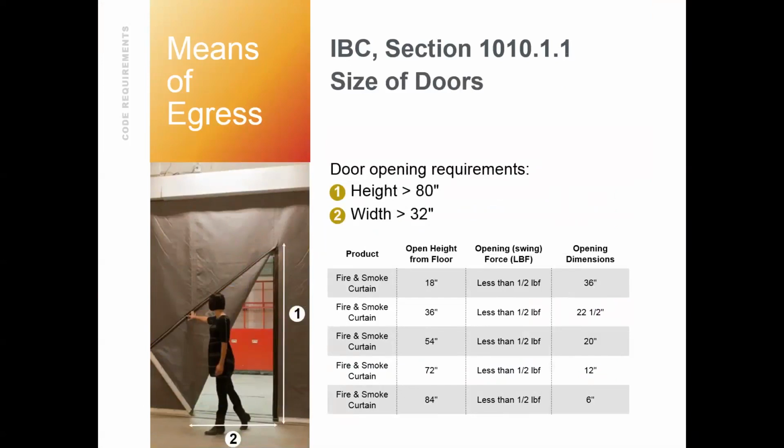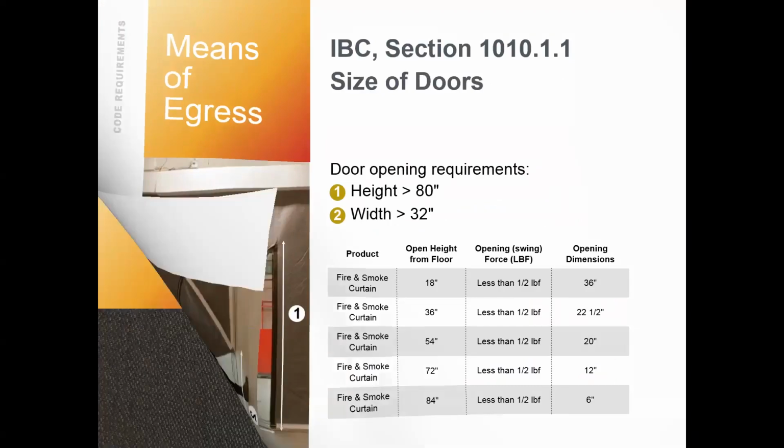In theory, all these doors at 80 inches above the finished floor are supposed to be 32 inches wide. That's by code. The reality is we just don't have a weighted bottom bar that's able to be sealed across this full opening curtain width. We can't get that bottom bar to seal it shut. But let me tell you, if anyone wants to come up with some ideas, I've got all afternoon. If we come up with this, we could sell it back to a manufacturer and be loaded. Trust me. Anyways, let me know. So it passes 2 out of the 3. Unfortunately, that has never been too much of a problem in trying to get it passed, especially from the side hinge swing pivot door motion specifically.